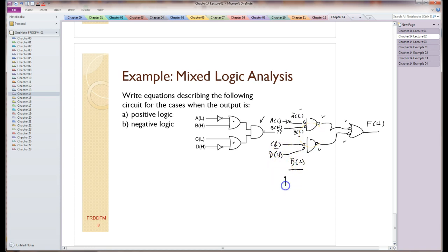So this is going to be F. These are AND functions, A naught, B naught, being ORed together with this OR gate here, and this is going to be C or D naught. So I just put square brackets there. Okay, I'm going to check and verify this is right. Yeah, looks fine. Alright, hope that's okay.